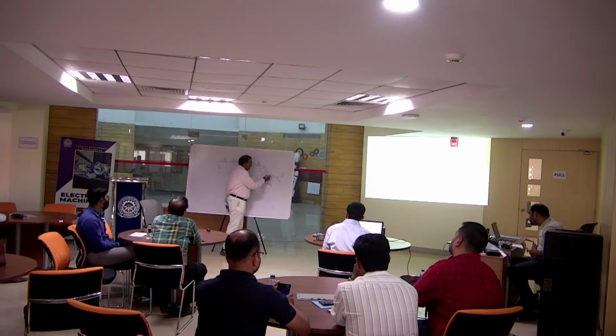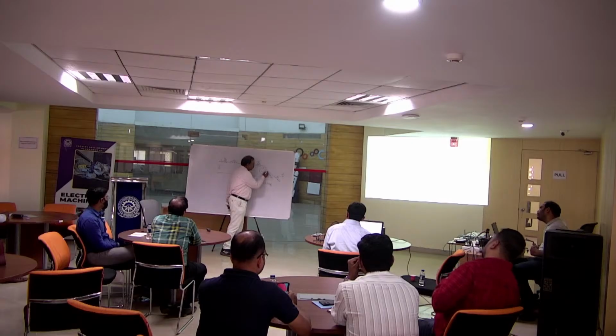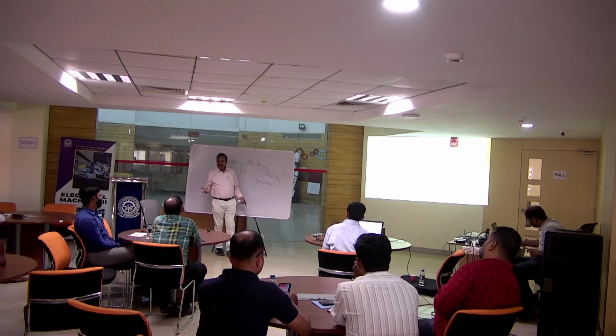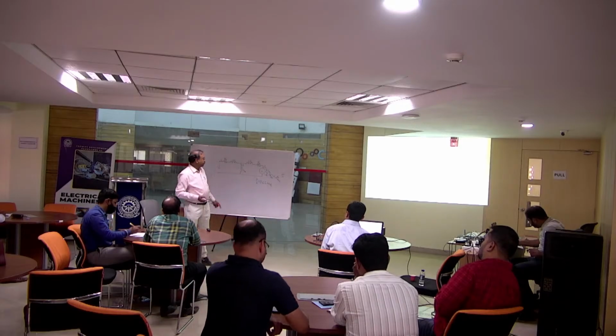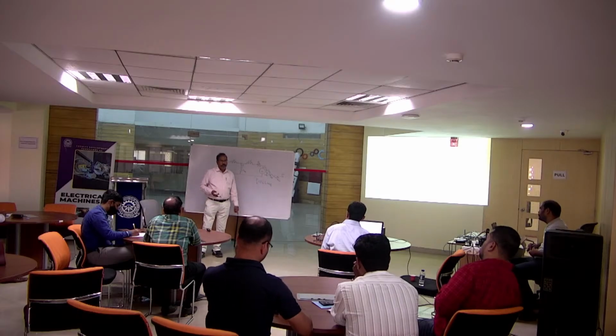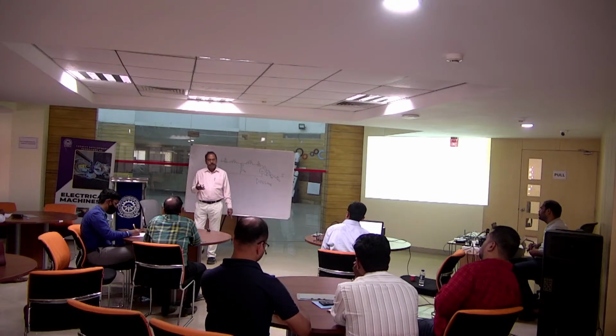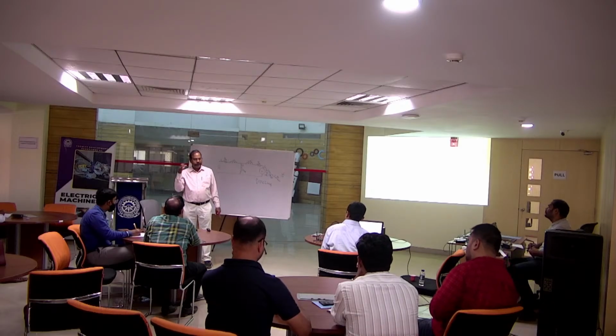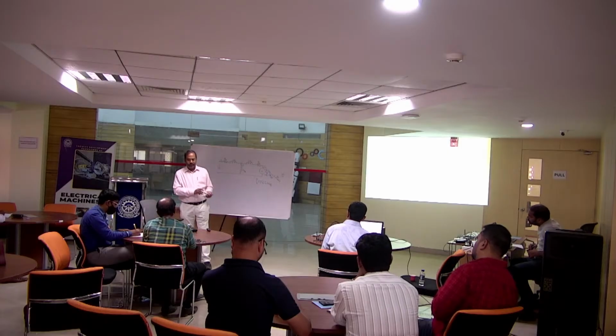This is IR. There can be another current here also. This is IR1 and this is IR2. Another current also has a component. This component, same thing, will give power to the rotor circuit. So by controlling the magnitude of the voltage and the phase angle between the voltage and current, you can control the power, whether you are taking more power from the rotor or giving power to the rotor. So accordingly, speed will vary.